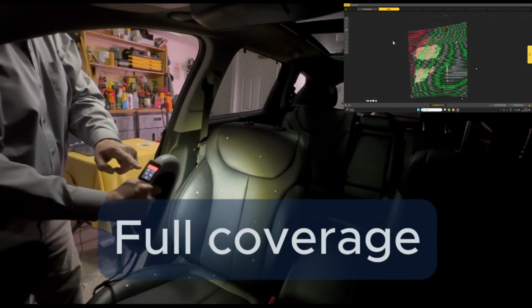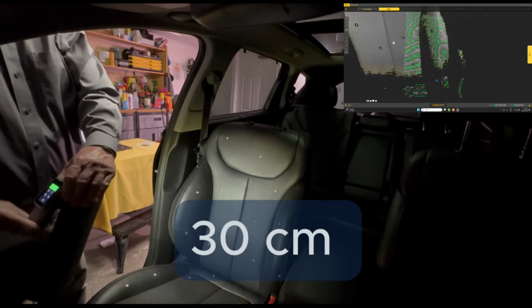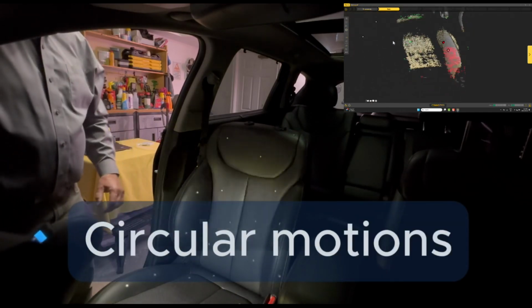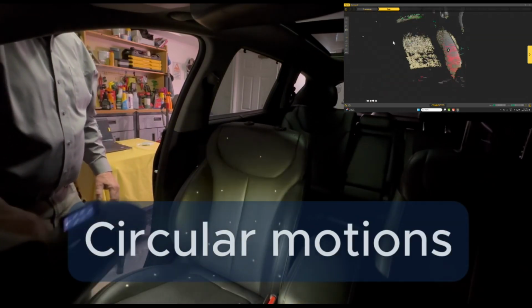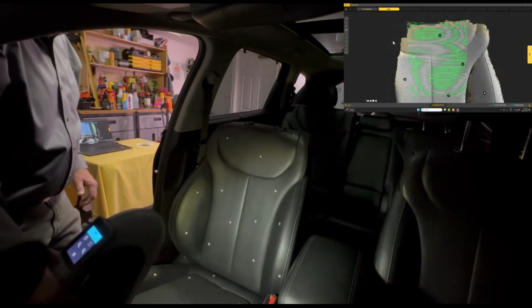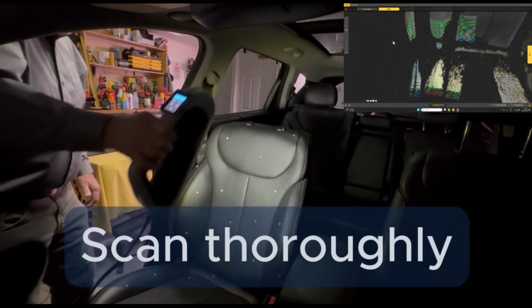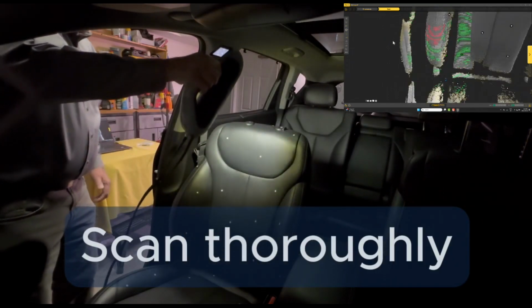You want to get full coverage, but not overscan. Ideally, you want to be about 30 centimeters away from your part. You want to rotate your hand slightly in a circular motion, and you want to constantly be moving the area of scanning to ensure you're not over scanning, but also spending enough time to sufficiently scan the part thoroughly so that there are no holes.